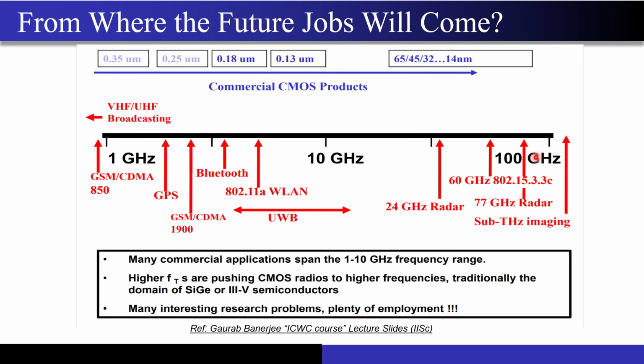Correct. Now how can you go to the 100, 200 gigahertz frequencies and still make your circuits work around those frequencies? The challenge is how to design the RF front end, that is the low noise amplifier and power amplifier, around 100, 200 gigahertz. And once you solve that challenge, there is one more challenge. The data rate that has been targeted around these bands is absolutely crazy. I'm talking about the wireless links. That data rate can go up to 30, 40 or even 50 gigabits per second.